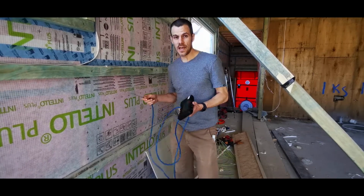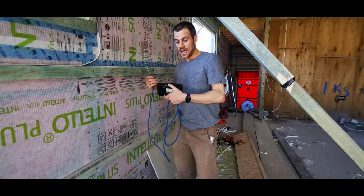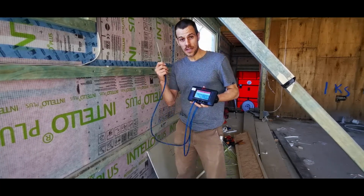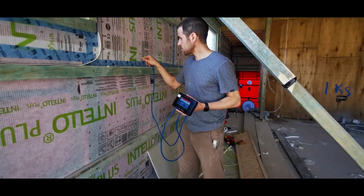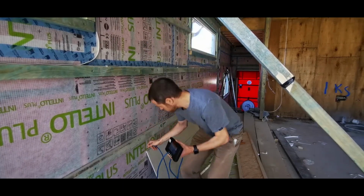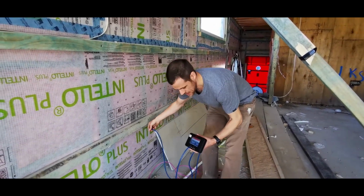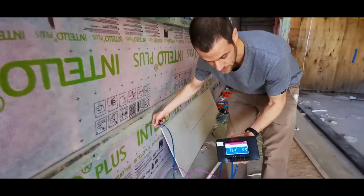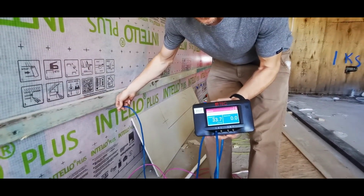So even if you only have one manometer, you take that manometer, bring it to 50 pascals, and then take the manometer from the blower door and bring it in your hand with one of these steel pokers and poke it right through the membrane and read what is the pressure across there. So we've got 33 pascals.